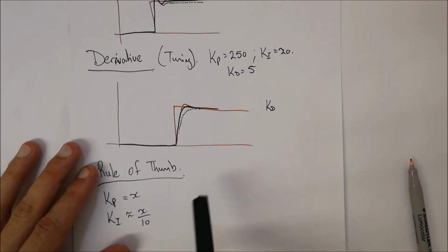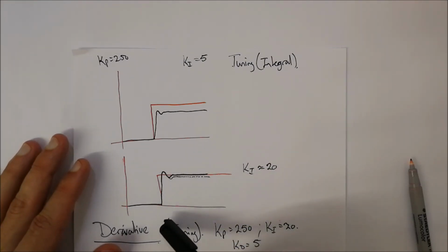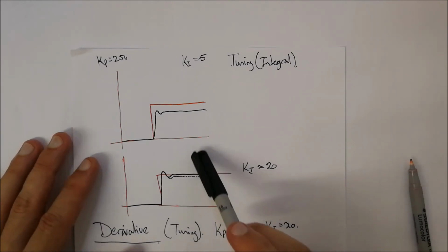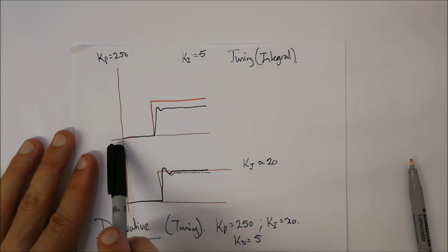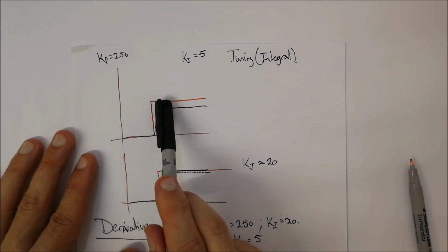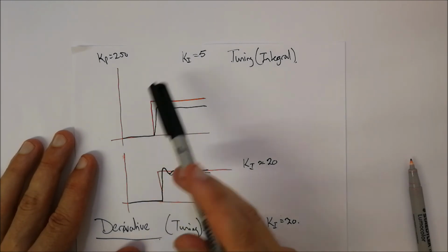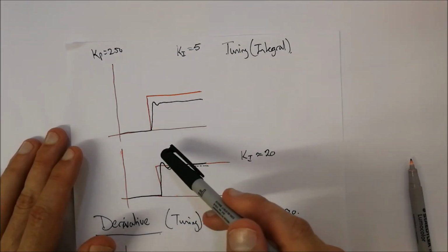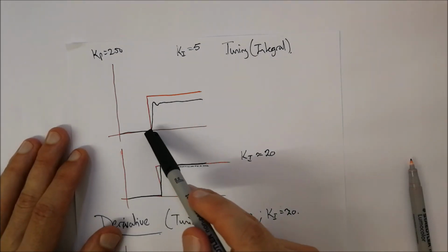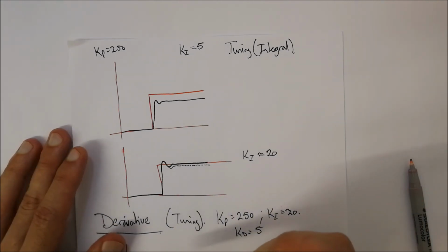Okay, sometimes you'll find that with a certain proportional controller, like I mentioned to you, you've got your PD controllers. Maybe you don't even need the integration one. Maybe the Kp value is sufficient. There isn't much of an overshoot for that specific system. It gets your set point, but you want to eliminate that overshoot. And therefore you use your PD controllers. So you would not have the integration term to worry about, and therefore you are able to get a good graph by eliminating the integration term.